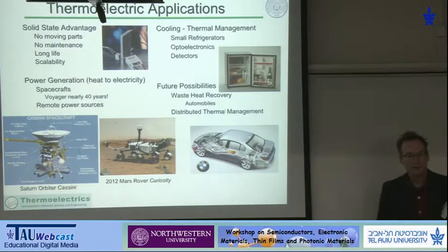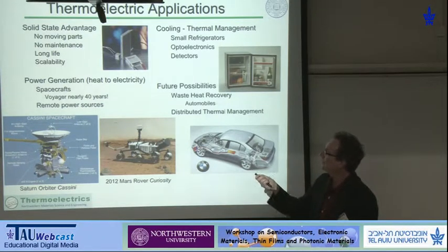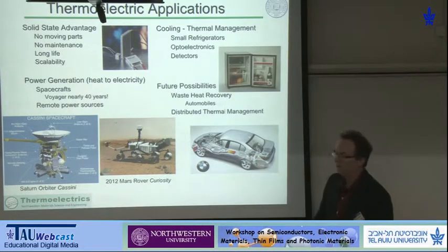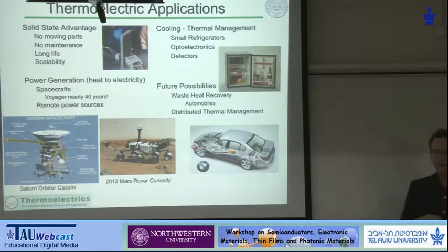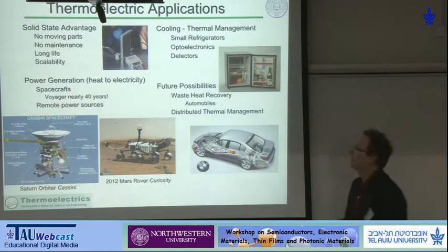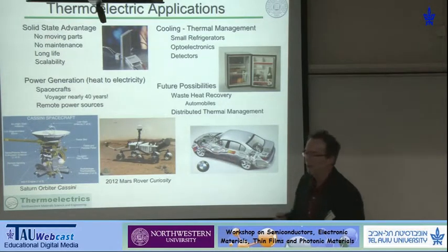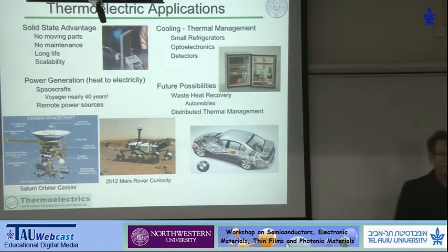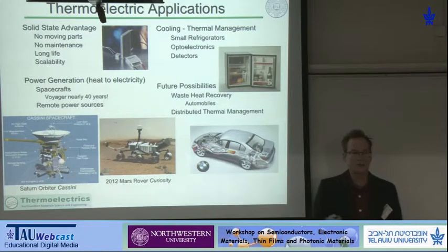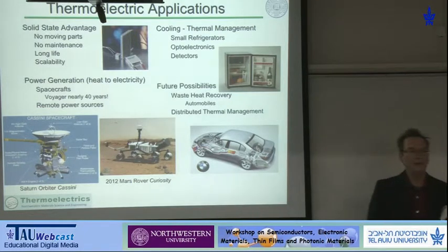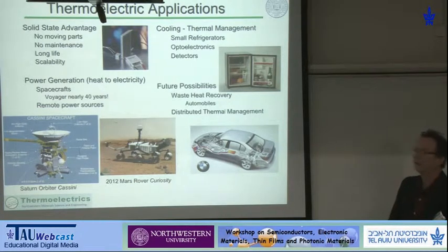So in traditional thermoelectrics, we have many applications that are known today. Most of our thermoelectric applications are in cooling, where the solid state advantage allows us to be in systems where we can do precise temperature control, even though we don't have quite the coefficient of performance.